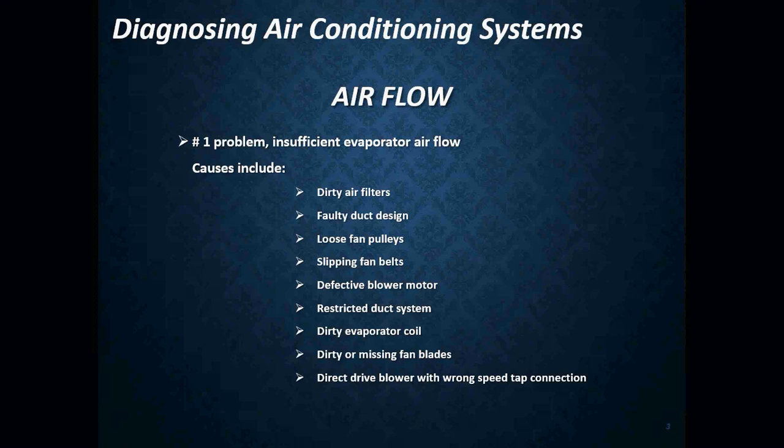Now, a lot of causes is going to be like we say here. It's going to be a lot of dirty air filters. It's going to be faulty duct design just from the get-go, which is hopefully going to be caught in the beginning stages of installation or within the first maybe month or so of operation of this piece of equipment, that maybe there was a design flaw in the ductwork. Hopefully, if somebody's doing their math right and didn't forget a takeoff or a room, for example, in a home, hopefully the ductwork is designed correctly right from the very beginning.